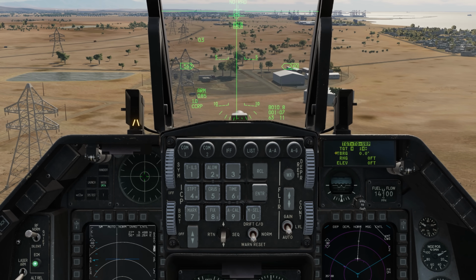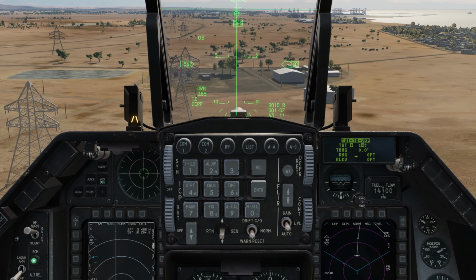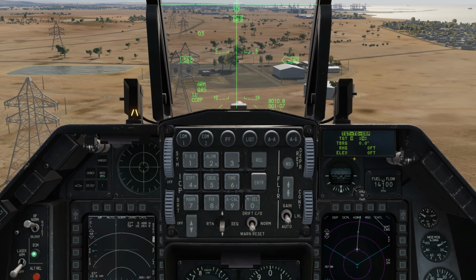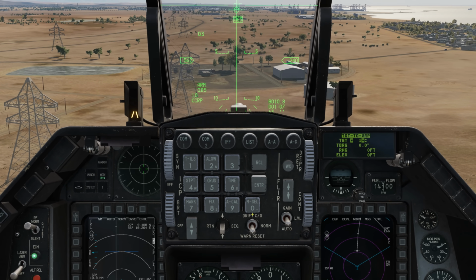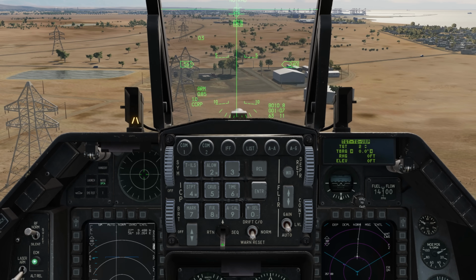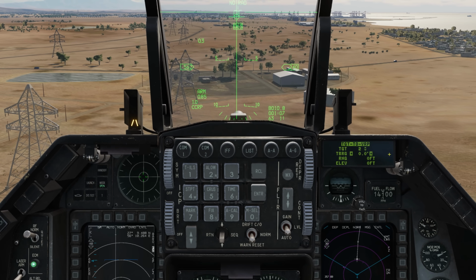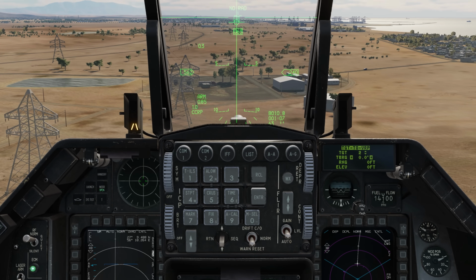Dauber down. First we have our target, and the target again is going to be the same location as the selected steer point. In this case, I want the target to be the same location as steer point 2. So I'm going to go increment up on the rocker, dauber down. Then we have our target bearing, and this is going to be the bearing from the target / steer point to the reference point.